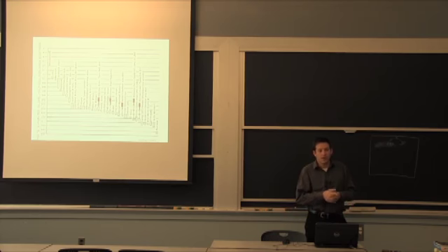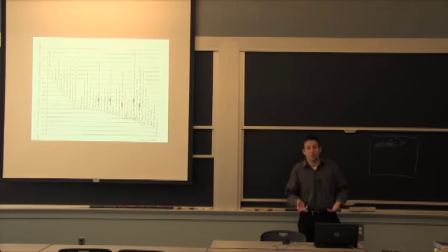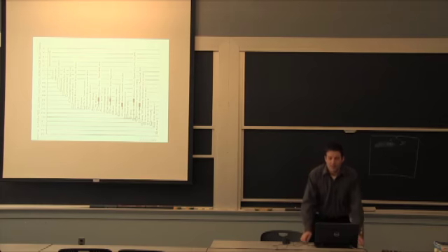Now, if you have an environment, and we'll go to that very shortly, where the aluminum is going to be at low pH or high pH, then it will disappear on you very quickly. And I've seen that on roofs where, again, they used some cleaning products. They had this large beam, and the beam pretty much disappeared because it was in a strong chemical environment for an extended period of time.